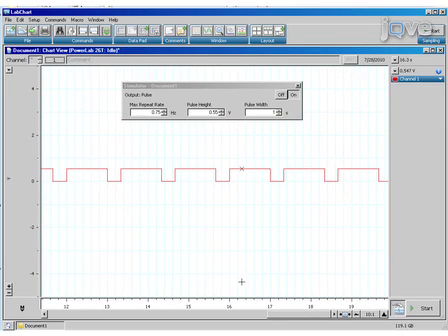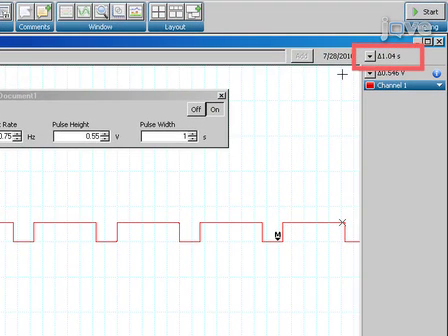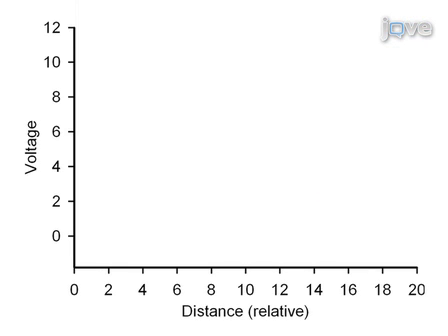Measure the saved voltage differences on the traces stored on the computer by using the cursor to move the trace to each pulse recorded. Use the M marker cursor, found in the lower left corner, to mark the bottom of the trace and place the free cursor at the peak of the trace to measure voltage difference. Read the voltage difference measurement from the screen and write it in your notebook for each measurement location along the circuitry. The next step is to calculate the length constant for the model cell, which is used to describe the exponential decay of the signal over distance.